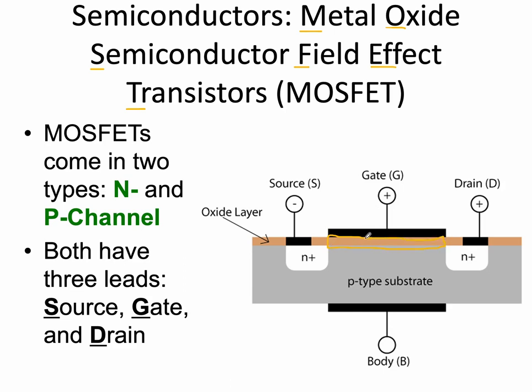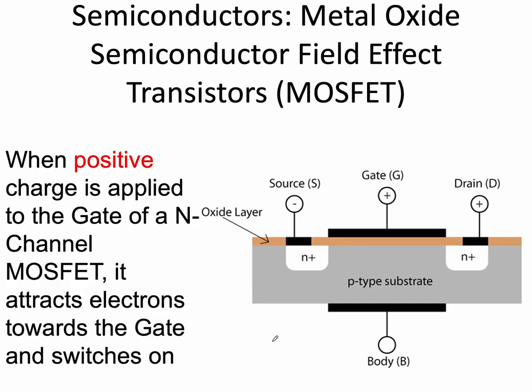And you're like, whoa, whoa, what's going on here? Well, this is sort of like a transistor, but something interesting happens here. If you apply a positive voltage to the gate, you charge that metal positively, it attracts electrons towards that gate. Well, you've got excess electrons here now, and even in P-type silicon, you still have some electrons that are mobile.